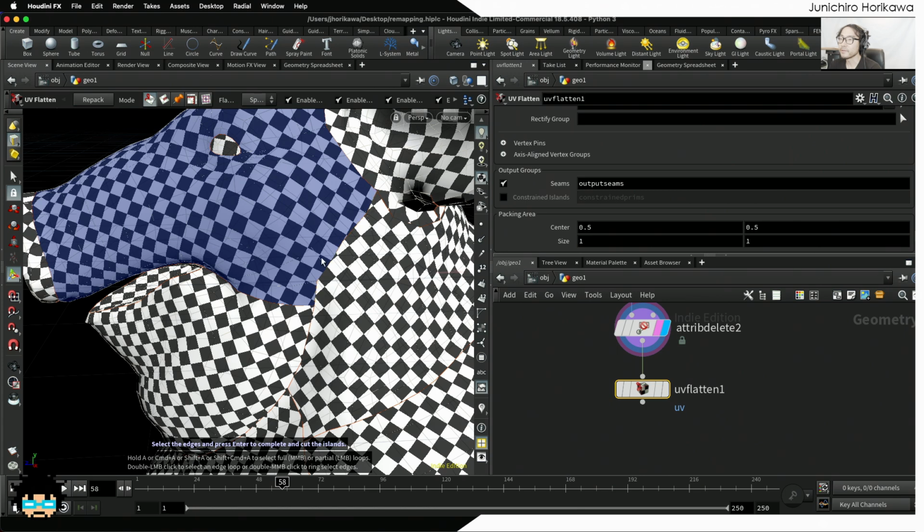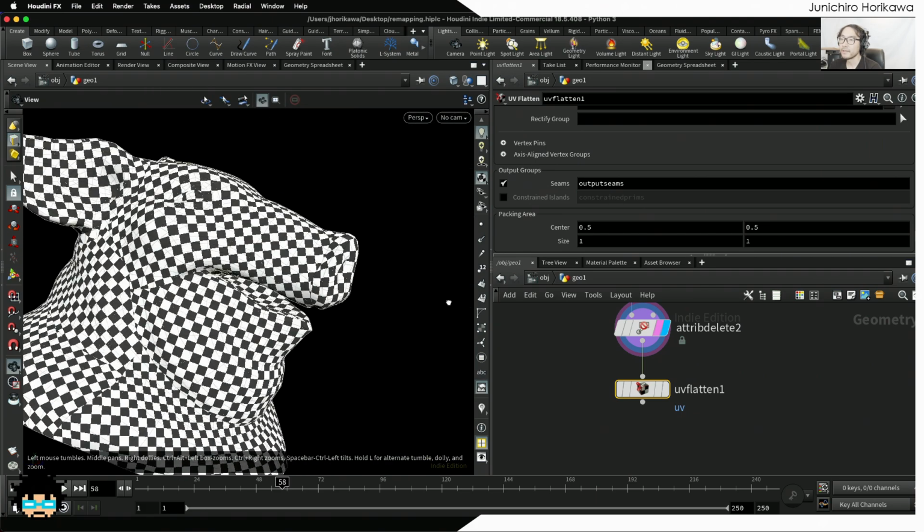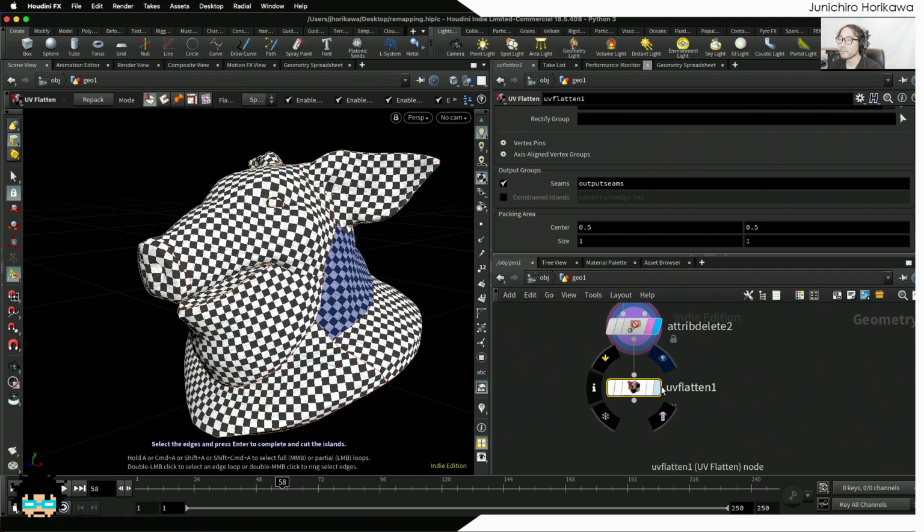So I want to trim out or split those surfaces where you have the seam. What I would like to do is flatten all these planes into a surface as geometry using a wrangle or VEX.